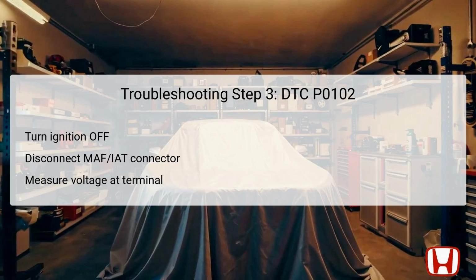Should battery voltage be absent, it implies there is an open wire or potential fault leading back to the PGM-FI main relay. Addressing this wiring issue is necessary before proceeding with verification steps. Consistent voltage readings help in diagnosing effective MAF operation.